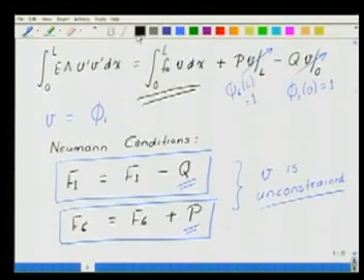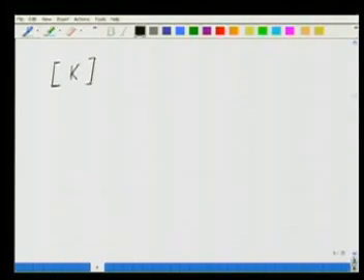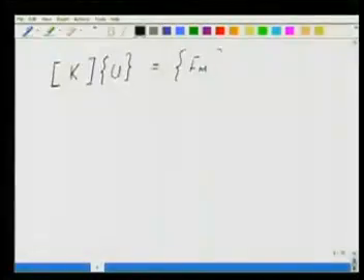What does that mean? Remember that there is no geometric constraint to be imposed. So, we take the original K that we got out of assembly, keep it, and the load vector will be modified, the one which we obtained by the previous step.